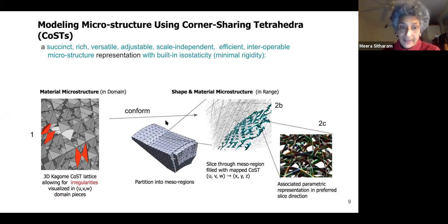And then this is a humongous thing. You might have a 1 meter cube of tiny microstructure, maybe of the scale of 1 micron, or 10 microns, let's say. So you have this huge thing, which is irregular, and it's not periodic, and you want to be able to print it. Printing is typically still done by slices. How the slice is processed is changing. Typically, the slice used to be processed by one nozzle following a path along that slice. Nowadays they have multiple nozzles, but still a constant number of nozzles depositing the material, or there are others which melt the material, but still it's melted in particular places. So at best, an entire slice may be printable at the same time, but it's still done in slices.